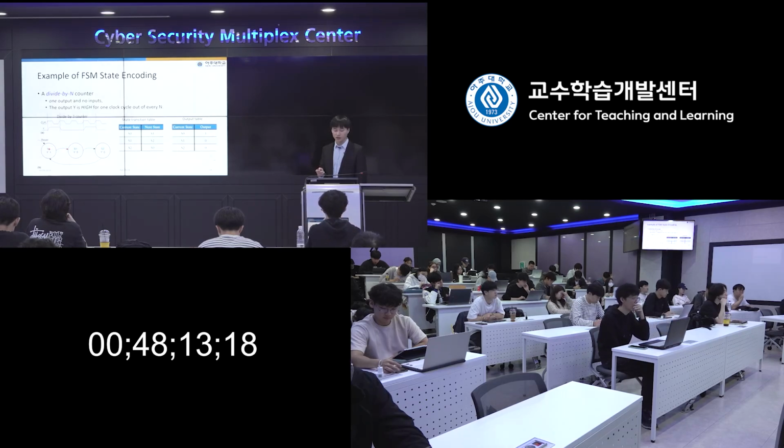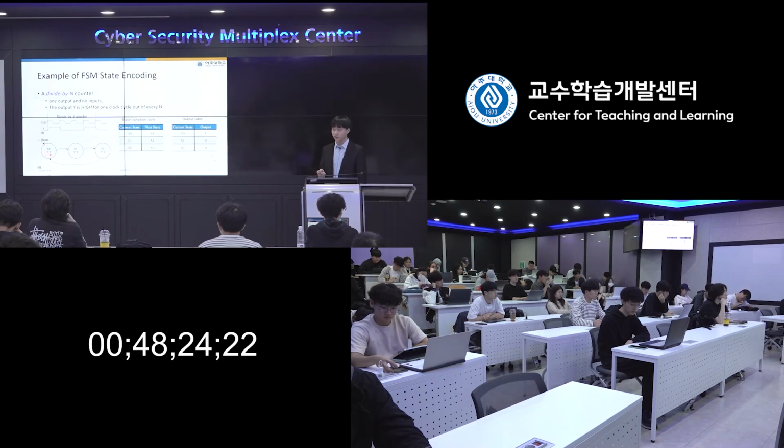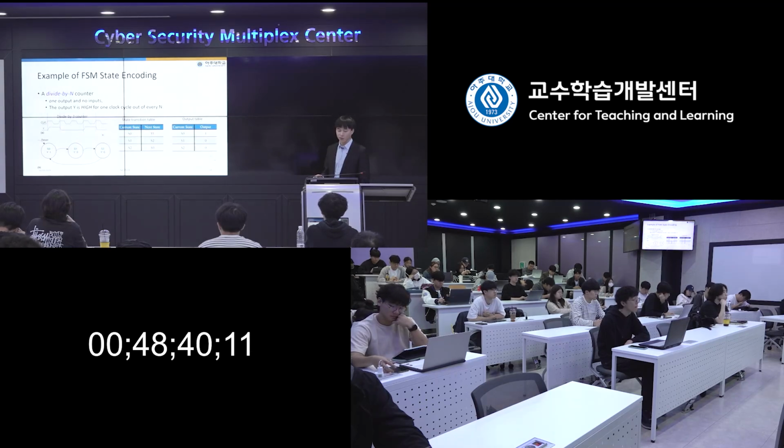So then it just switches from S0 to S1, S1 to S2, and S2 back to S0, because we already have the period of 3, then it outputs y equals 1. So a very simple state transition diagram. And with this state transition diagram, we can build the state transition table and output table together. It's simple, right? Current state, next state: S0, and the next state is S1; S1, S2; S2, S0. One by one, we can write down here.